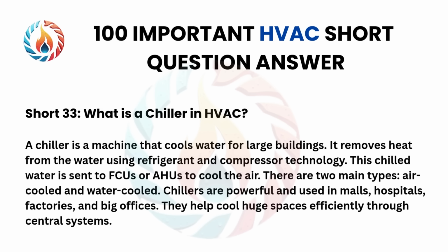Short 33. What is a chiller in HVAC? A chiller is a machine that cools water for large buildings. It removes heat from the water using refrigerant and compressor technology. This chilled water is sent to FCUs or AHUs to cool the air.